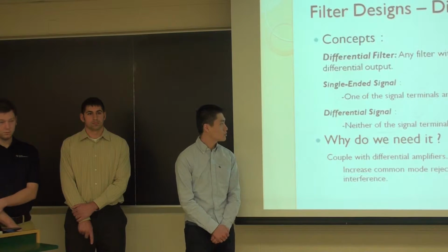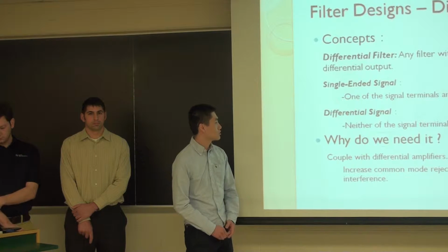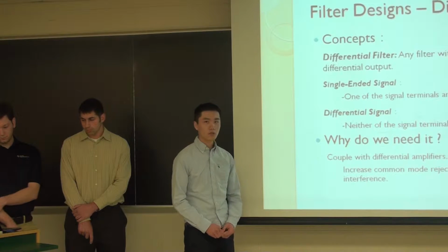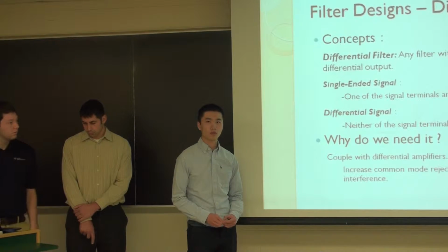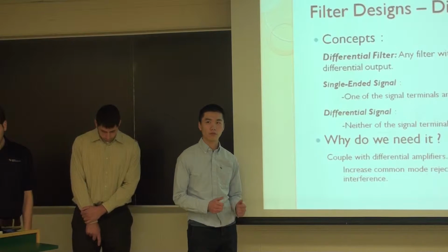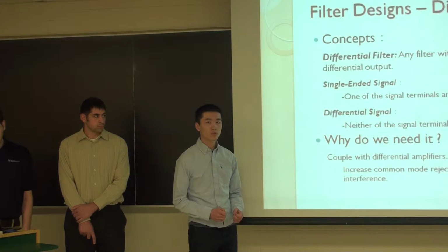Why do we need to use differential signals? Actually, in the real world, there are many differential signals. For example, in our project, the ECG signals we get from the thumb pads are differential signals. We want to differentially amplify them.